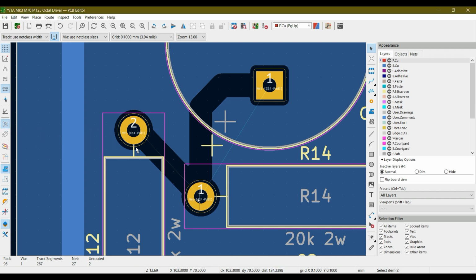You can see over here these are two thin lines which are actually called the ratsnest. So once you import your schematic, you will see a bunch of these lines specifying the connections between the components. These are called ratsnest. By using this display option, you can either show your board ratsnest or not. After this, the next setting is also associated with the ratsnest. It is show ratsnest with curved lines. If you click on this, you can see that our ratsnest is converted into curved lines. Now this is a straight line, this is a curved line. These are all the display options. So let's just press Control Z to redraw our tracks.